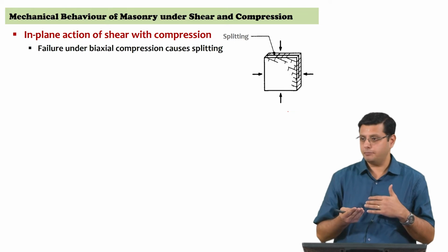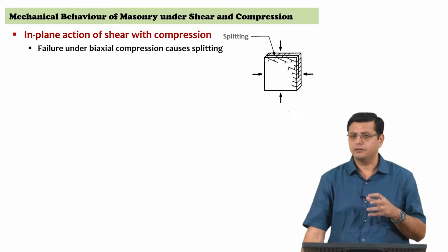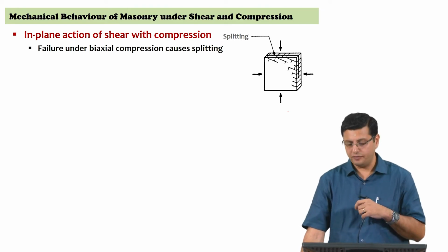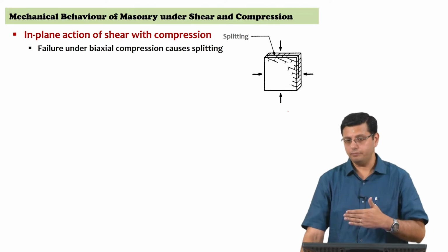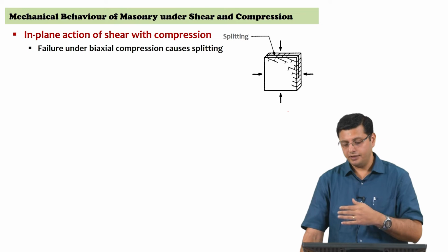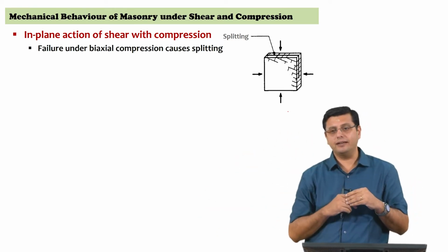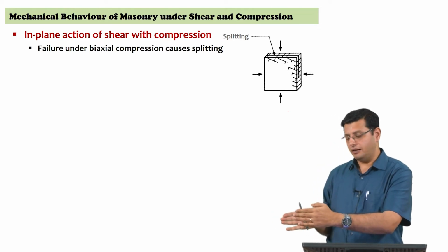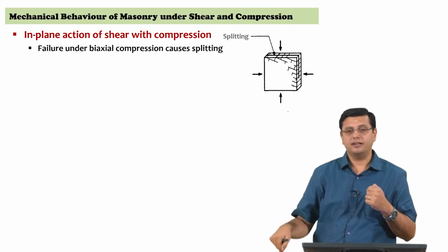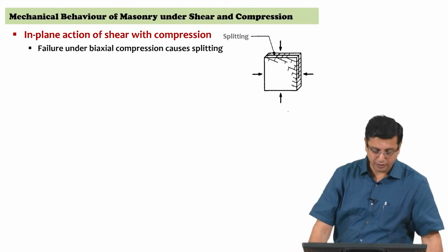It is very difficult to imagine that masonry can fail in this manner, and it is interesting because you will wonder in what conditions you would expect this sort of compression state occurring in a masonry wall panel. We have seen this sort of failure in a regular load bearing masonry wall. We were working with a reinforced masonry wall, and when it was subjected to lateral forces and gravity forces in our laboratory, the toe block, where maximum compression occurs as the wall deforms laterally, because of the confinement provided by the reinforcement and the hollow block at the edge, actually had compression in two directions. There was compression due to gravity and compression in the other direction, and there was vertical splitting as you see in the end blocks.